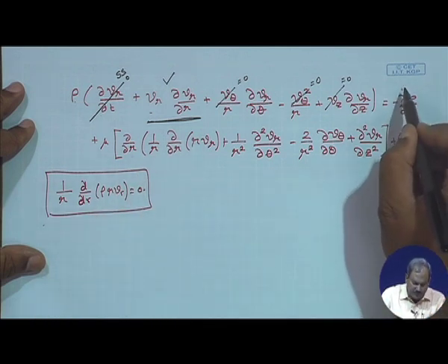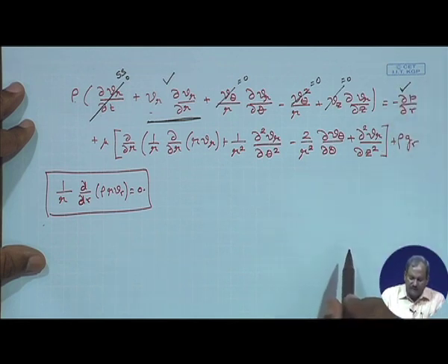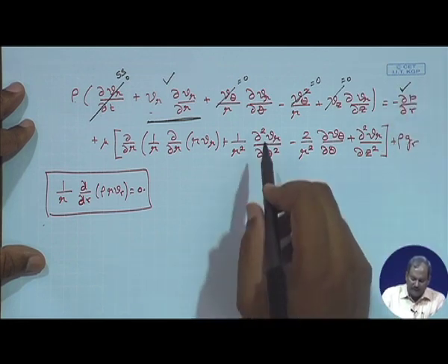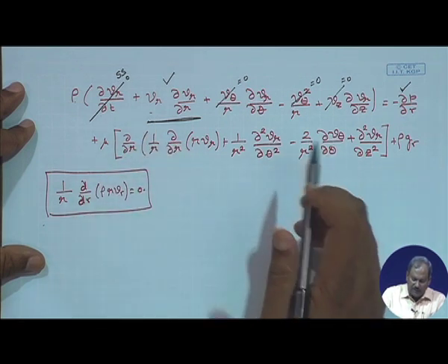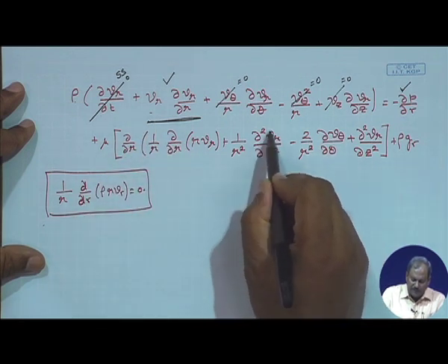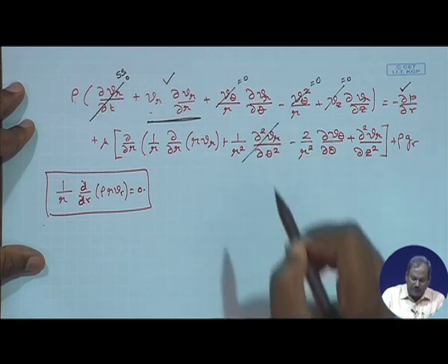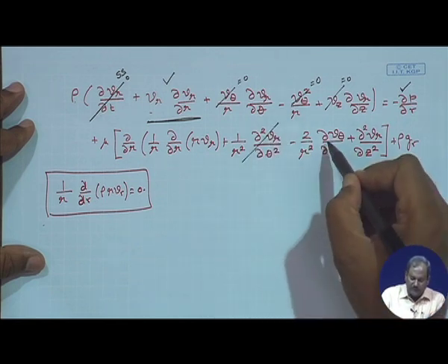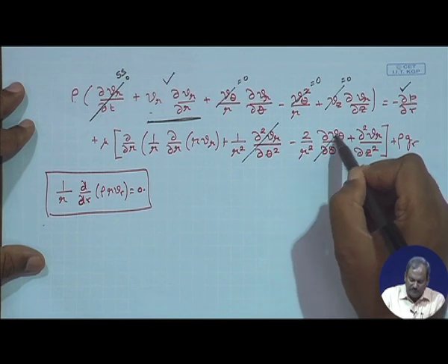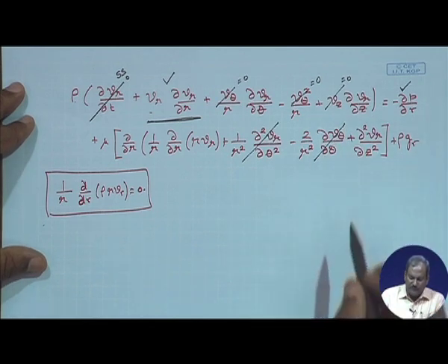There is a fixed pressure gradient present in the system. So, I must keep del P del r in here. I will come to this at a later point. If I think of this term, Vr is not a function of theta. So, therefore, this is going to be 0. There is no V theta present in the system. So, this term would also be 0.